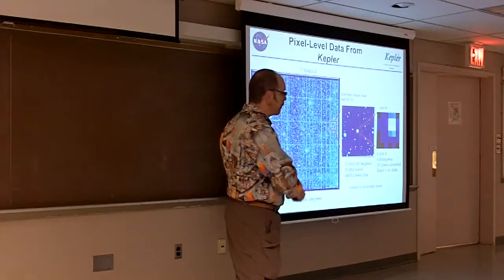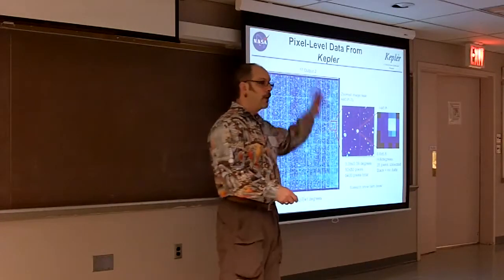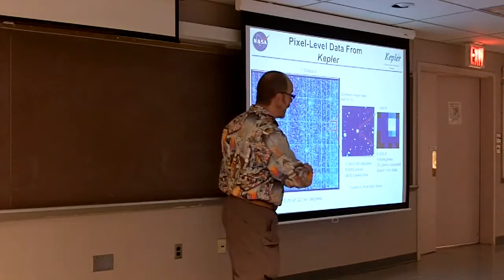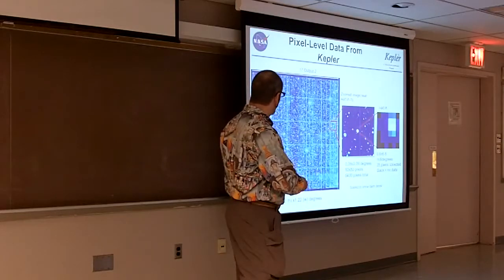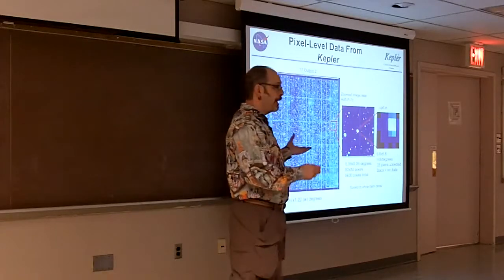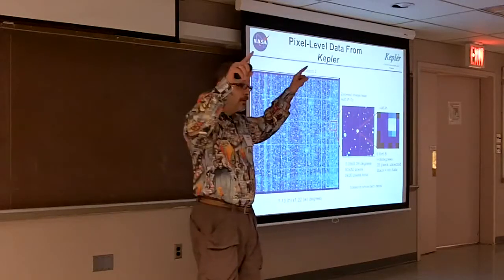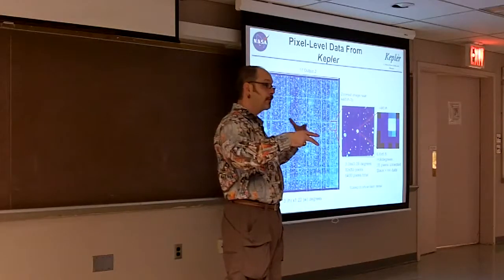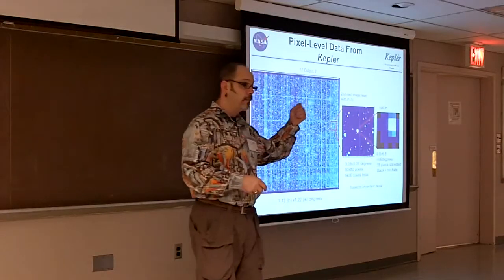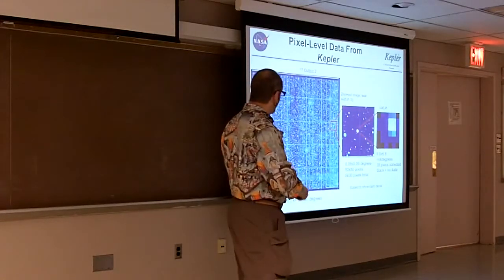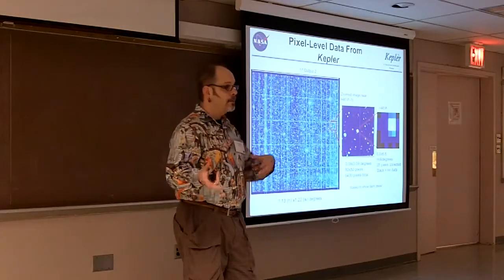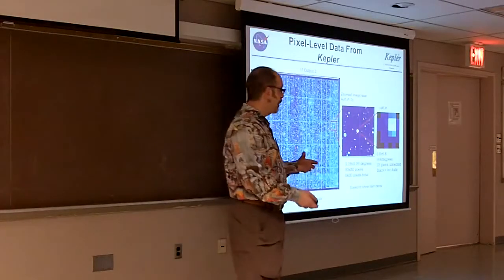So to first order, the smear tails are uniform and constant along each column, but they vary over time and vary from column to column. So we have 2 special regions we use to measure that and subtract it off as part of the pixel level calibrations. The other feature you can see are these horizontal features. Those are caused by the clock signals driving the fine guidance sensors that are in the corners of our focal plane, and they're causing small DC offsets when each of these pixels is being digitized through the analog to digital converter. And it's a synchronous system, so this represents fixed pattern noise that we measured before launch. We confirmed that it was still the same on orbit, and we model and remove it as part of our calibrations.